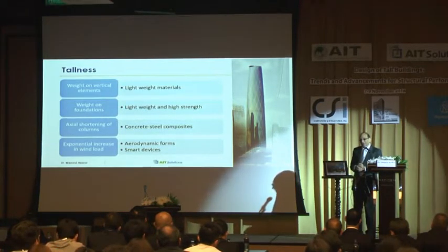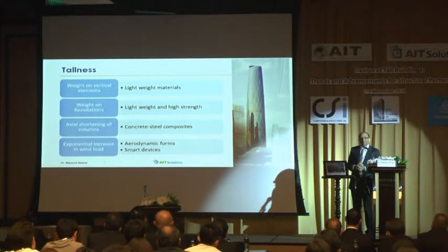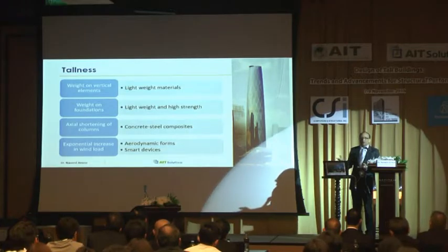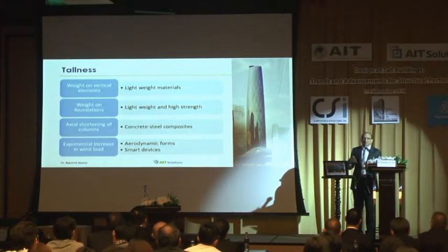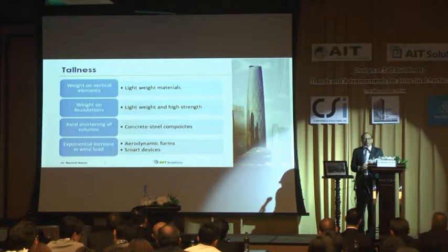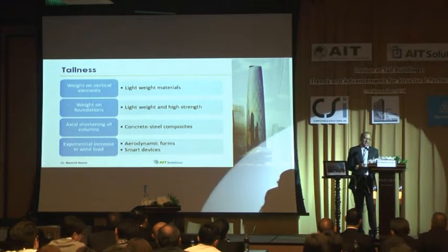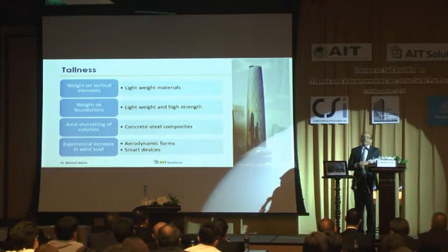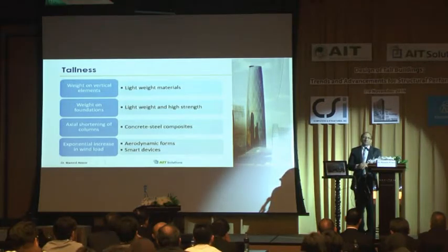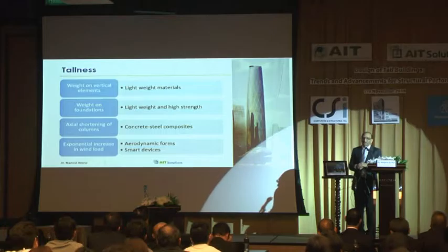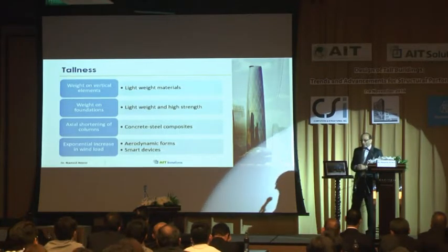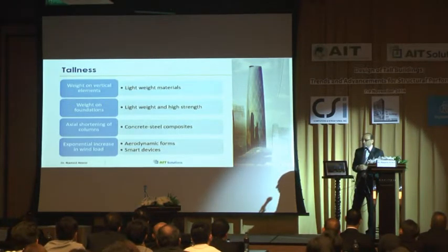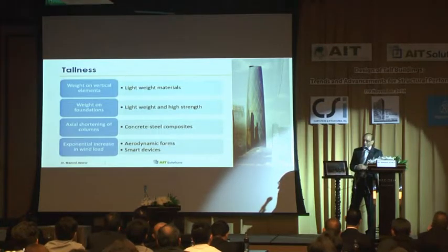Weight on the foundation is another challenge. The soil can only take so much. If the soil is not capable, if the bedrock is very far, like in Bangkok or other places, there's only so much you can do. In fact, the 600-meter tall building that Dr. Karoon did not present is being planned. One of the challenges is the foundation isn't strong enough. The soil just isn't there to take that building. Again, lightweight and high-strength materials could be an option.